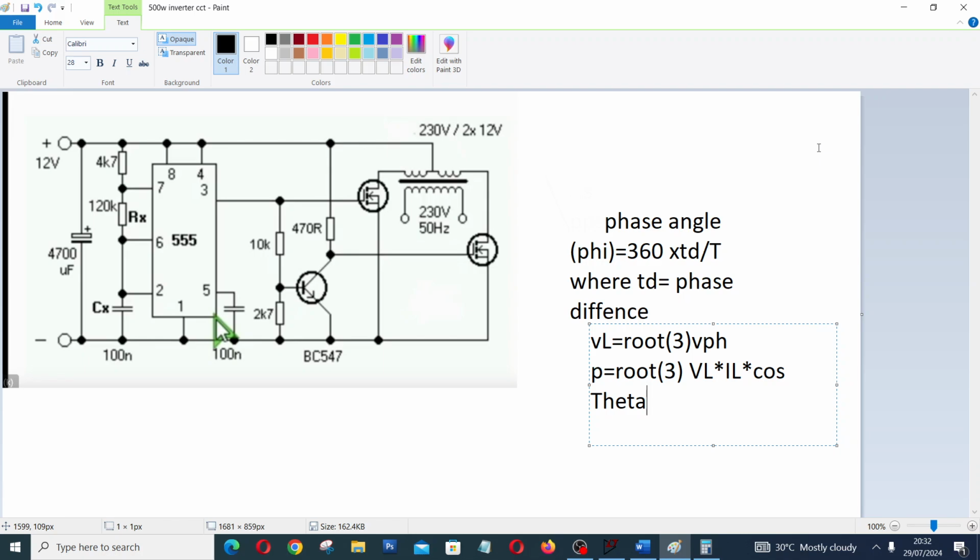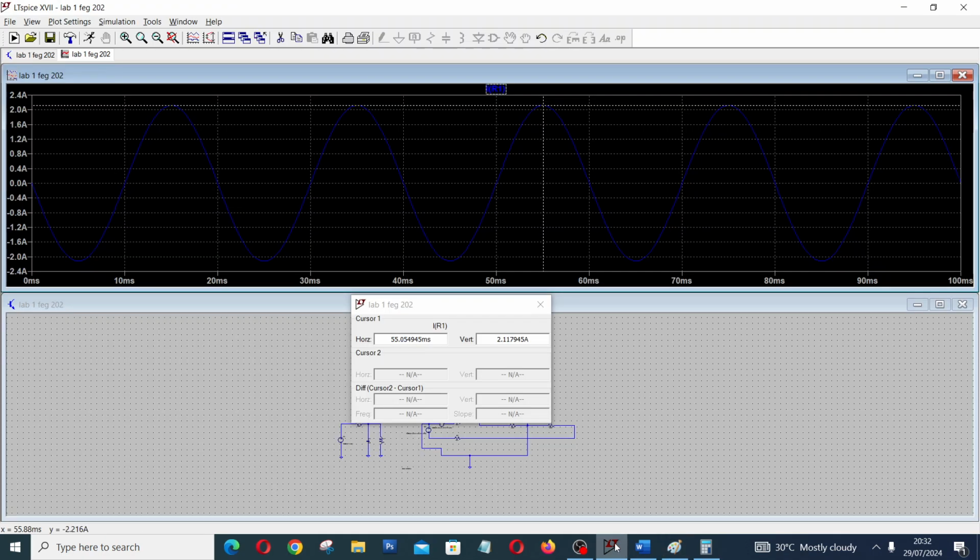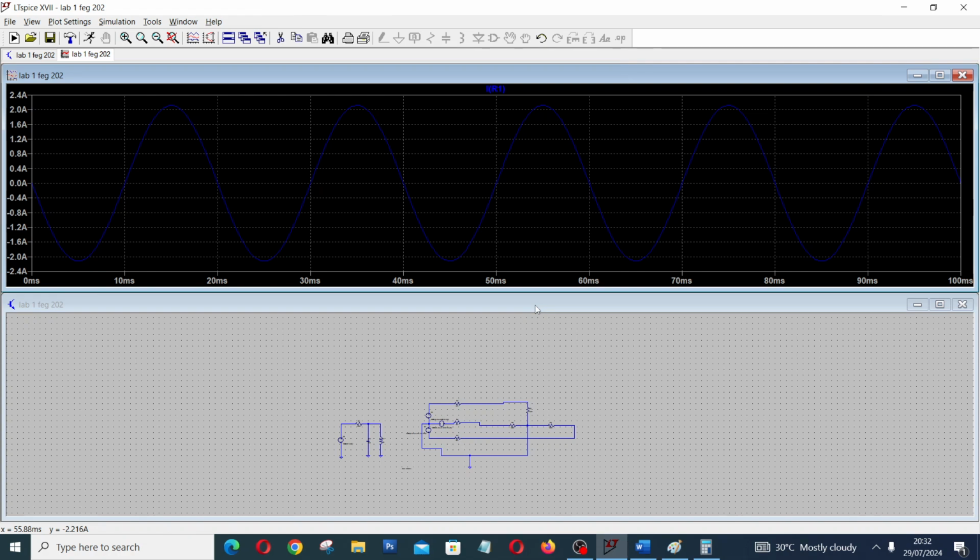So in the next video, I'm going to show you how we can improve power factor. You must have come across the issue of power factor. Power factor is not a problem in this experiment. We just finished running a balanced system, in the sense that there's no capacitor nor inductor in this circuit, and because of the absence of inductor, there is no lagging power factor, because the culprit to the power factor problem is actually the inductor. So when a system is too inductive, there tends to be what?